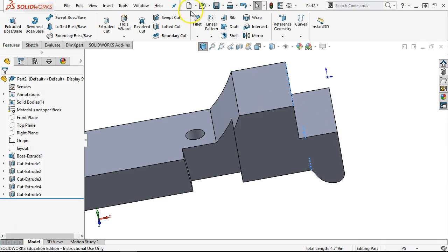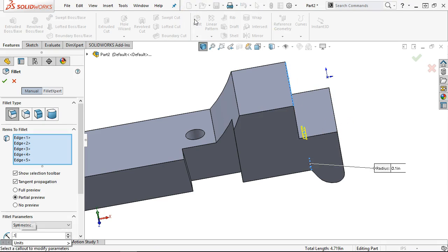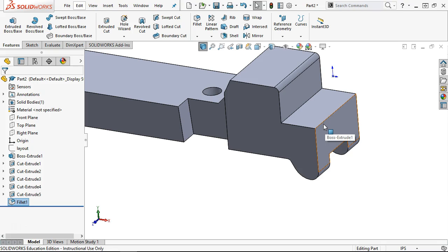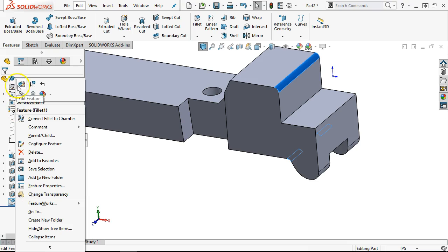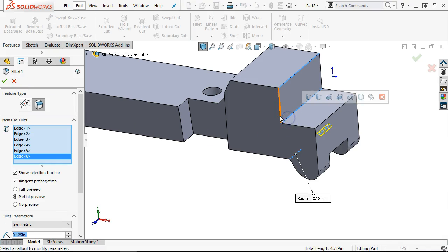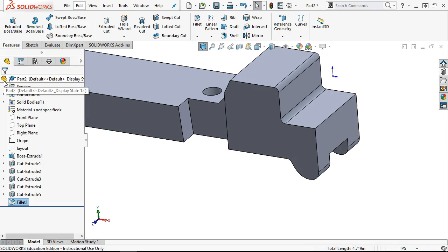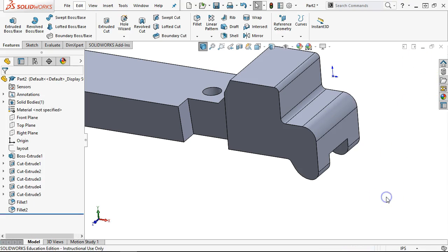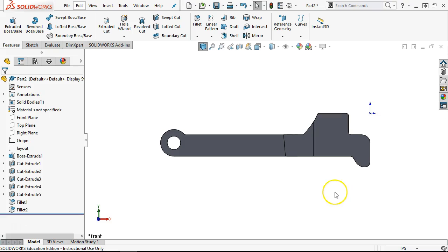Okay, we'll go ahead into the fillets. 0.125. And I could go back into the sketch and add the... actually, it looks like there is one in that corner. It doesn't call it out specifically, but assumption would be that it's probably there. And then fillet over the outside, 0.375. So I could go back into the sketch for that one and modify the sketch if needed.